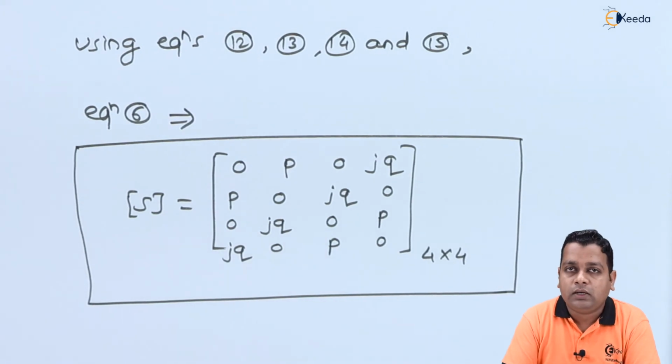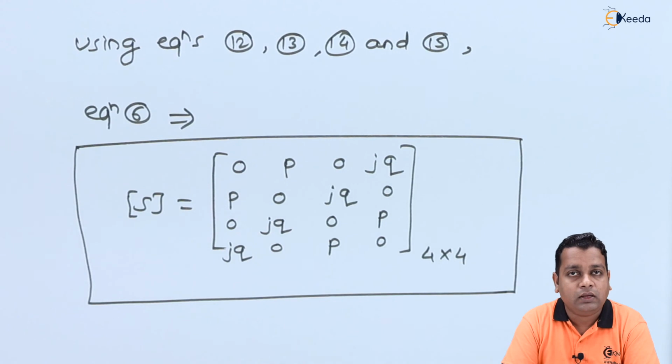So we can derive up to this particular point for the directional coupler, which is a 4-port passive microwave component. So this is the required scattering matrix, S matrix you can say. So based on the knowledge from the recent videos on the directional coupler and this one, in the next lecture we shall practice 2 simple problems based on directional couplers here.